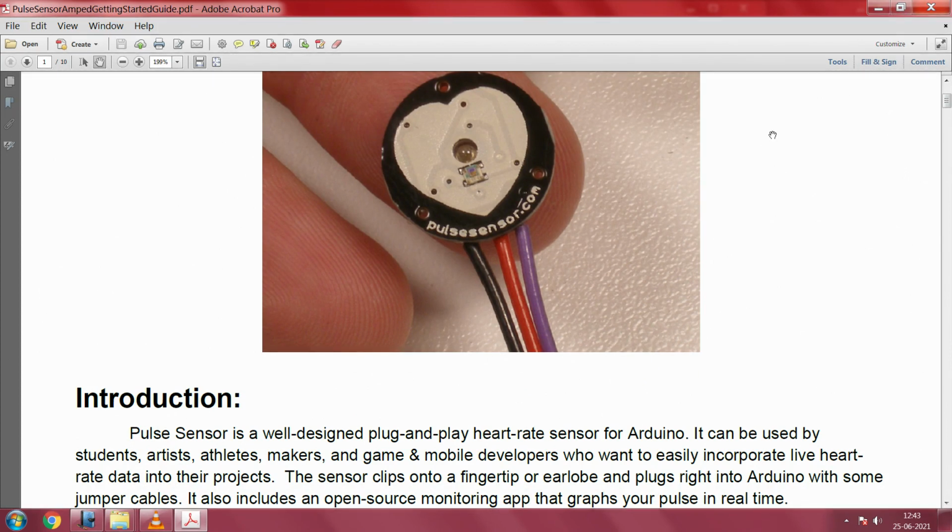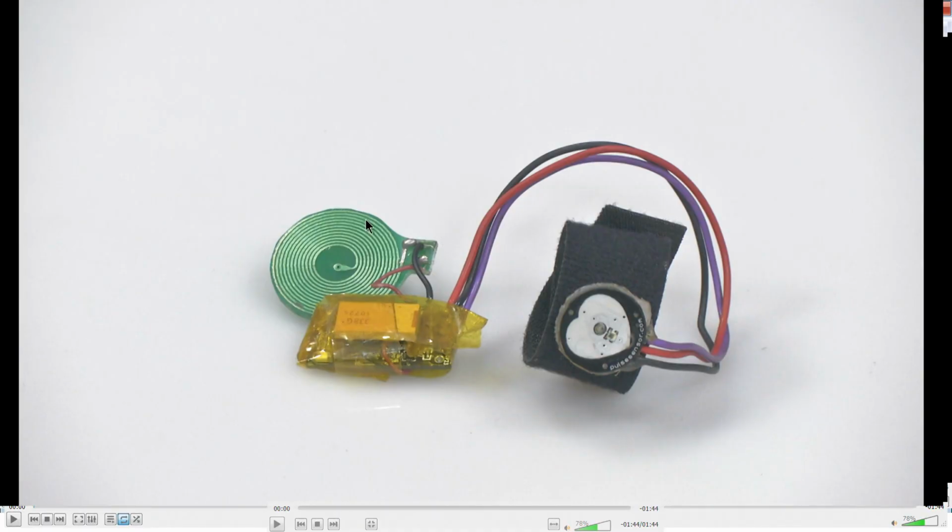The other part is to see an actual demonstration. How did we pull off this energy harvested pulse sensor measurement? Let us see the different parts that we have put. This one is an NFC coil. This is that 13.56 megahertz NFC coil, which is the receiver side. The transmitter is nothing but the mobile phone, and it is coming closer to this coil.